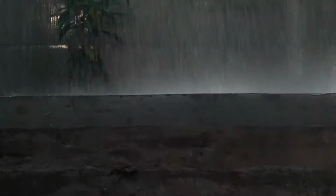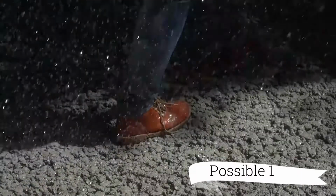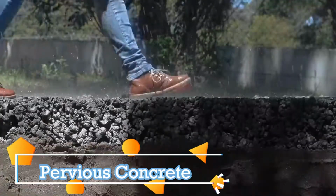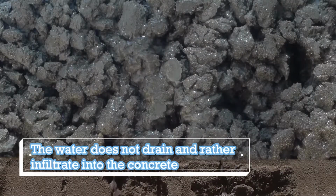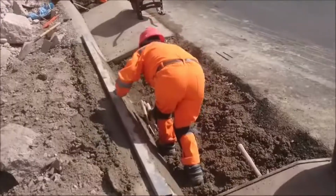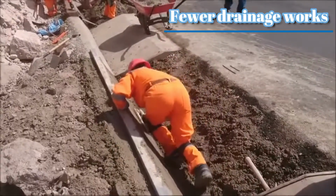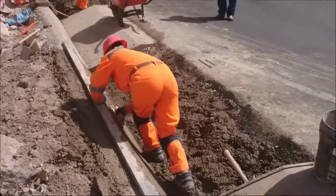Thus, while a conventional pavement is looking for impermeability with runoff factors as near as possible to 1, the pervious concrete seeks precisely the contrary. That is, the water does not drain and rather infiltrates into the concrete, which brings several advantages. For example, fewer drainage works, which in turn implies a reduction in the total cost of the work.